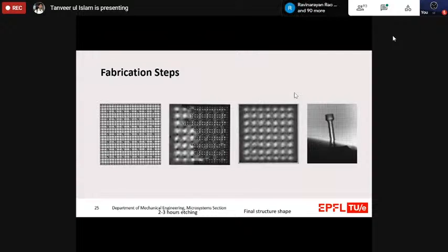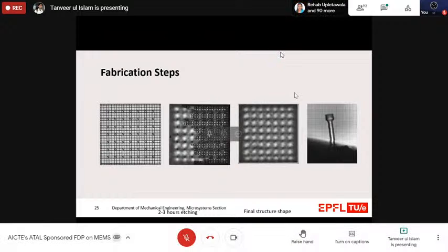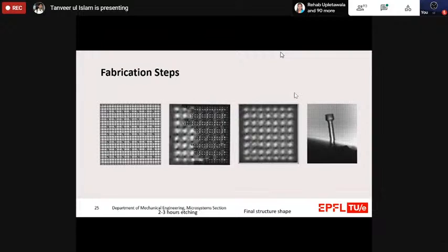On top of that, we have the system to be highly stable. There shouldn't be an effect of the ground vibrations. That could be achieved by setting the setup on a vibration isolation table, or we can have a very heavy system which dampens the ground vibrations and does not let that effect go into the material. That way, the laser will always be there, but you have good high resolution stages, and that will result in better feature size or shape.